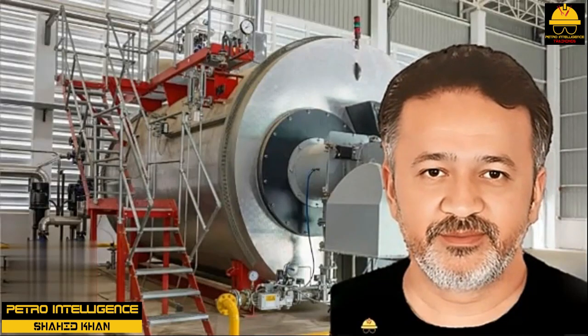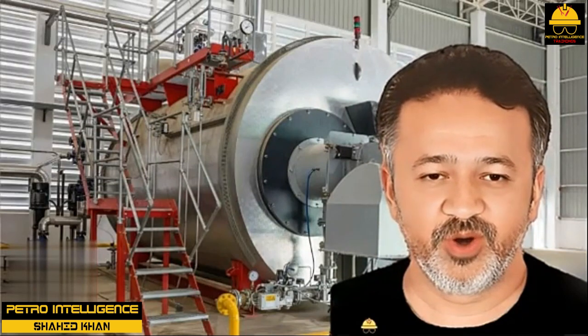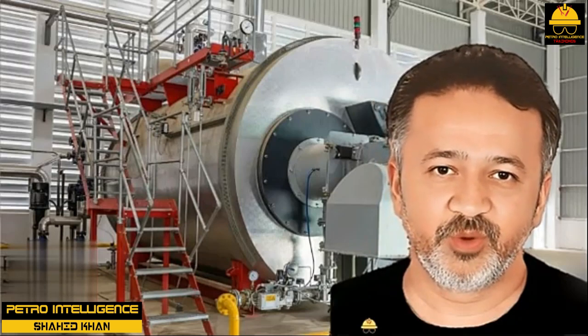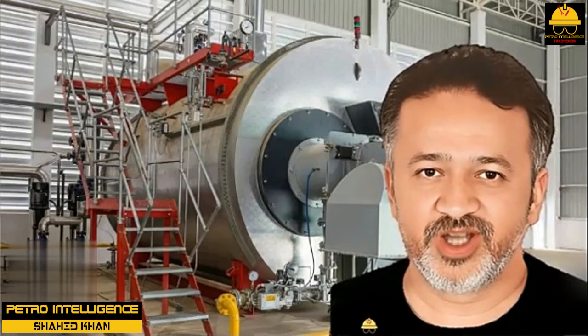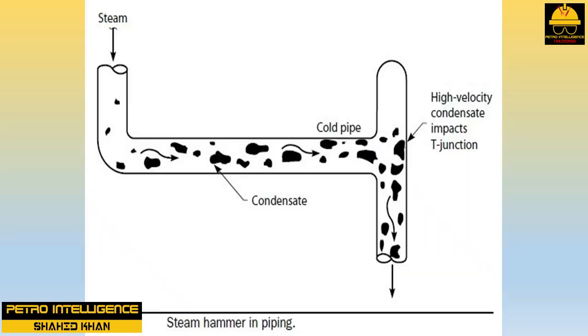Water hammer. Steam or water hammer, more properly called hydraulic hammer, is one process plant phenomenon familiar to the general public. When trying to warm up the steam system of a large amine plant in your plant, you can hear more than hearing the crescendo of crashes due to steam hammer. The cause of steam hammer is illustrated in this picture. In general, hydraulic hammer is caused by the sudden conversion of the velocity of a liquid into pressure, causing a surge of pressure inside a piping system.